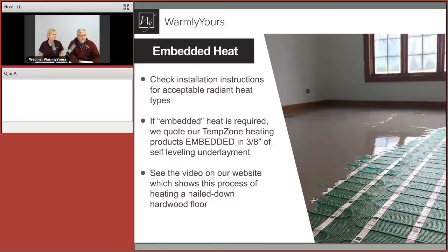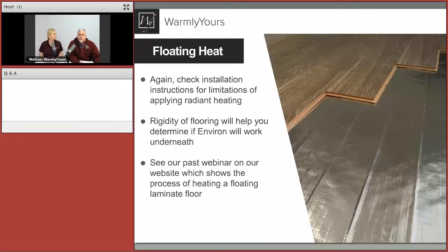So it's our recommendation to do self-leveling, but I will also tell you guys the most common way this is installed is with thin set. Right. Okay. And now for floating products, so this is under laminate, under engineered hardwood, and under carpet. These float between the subfloor and the final flooring surface. Anything else we need to know about that?